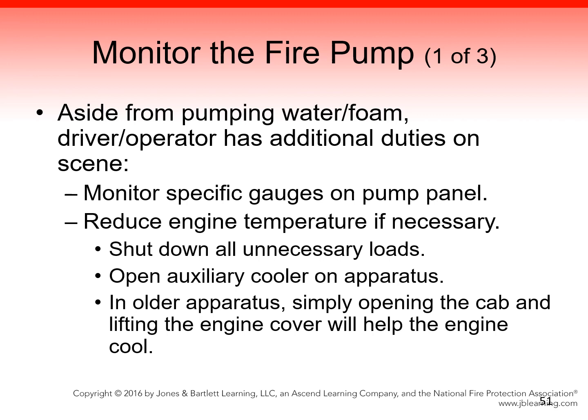Monitor the fire pump. As the driver-operator, you have additional duties and responsibilities on scene aside from pumping water or foam. Once the pumping operation is underway, you must monitor specific gauges on the pump panel, such as the oil pressure and engine temperature. During the pumping operation, if you discover that the engine temperature is increasing, you need to take steps to reduce this temperature.